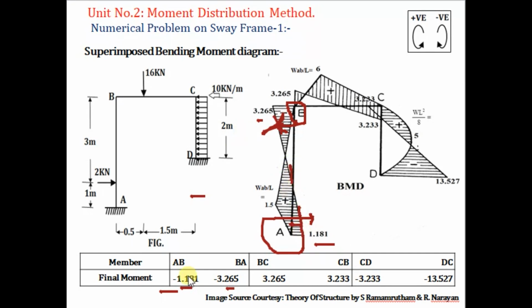Okay, so these two values, the end moment sign is negative, so when both end moments have the same sign, you see these values are opposite to the column. This column is vertical, one value is just to the left hand side and the second value is right hand side, so that means they are opposite to the column. Okay, so then you have to join with the line.